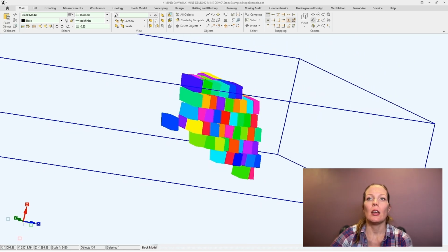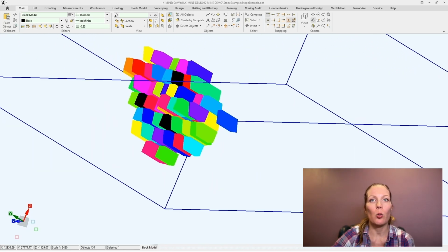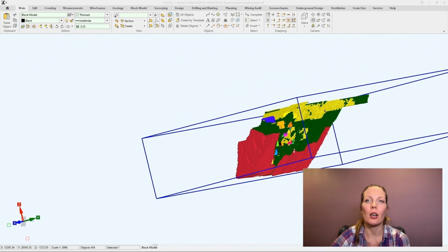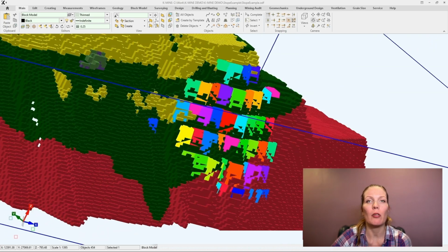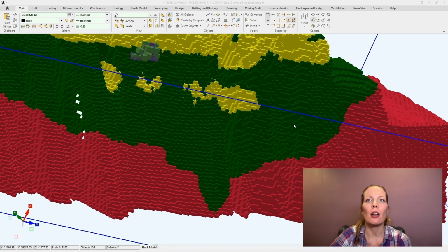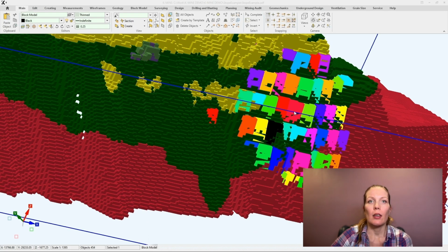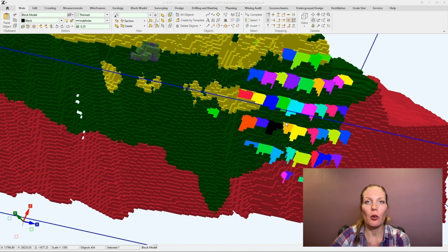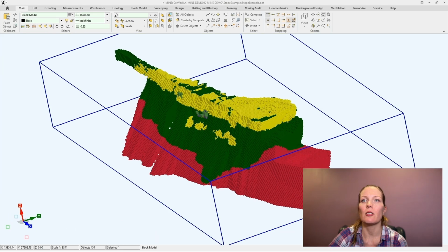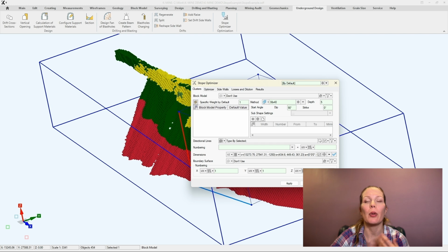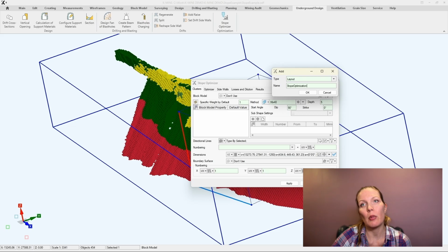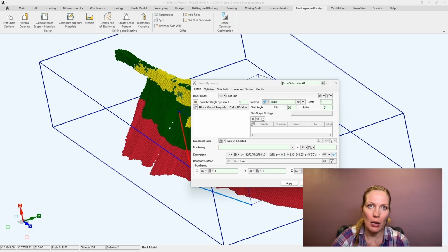In K-mine, the objective can be based either on quality or grade, or on economics. A grade-driven mode works well for highly variable vein deposits where securing metal content is the priority. The economic mode is often preferred for more homogeneous massive bodies. For example, clusters are evaluated against cutoff, prices, and cost, and only those that provide a positive economic contribution remain in the stope. This avoids carrying marginal volumes that would later need to be trimmed manually.